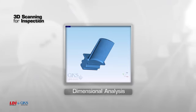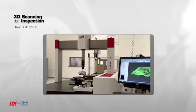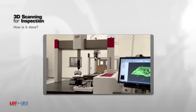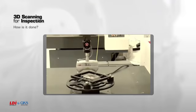There are 3 elements in 3D scanning for inspection: dimensional analysis, form analysis, and reporting. It's that simple. How do you do 3D scanning for inspection? Parts are arranged in a frame and placed on a gantry where the Surveyor 3D laser scanning system passes a line laser over each face and surface of the part. As you can see from the video, the part is rotated and the part is completely observed by the laser, and all of the points are collected in real time.